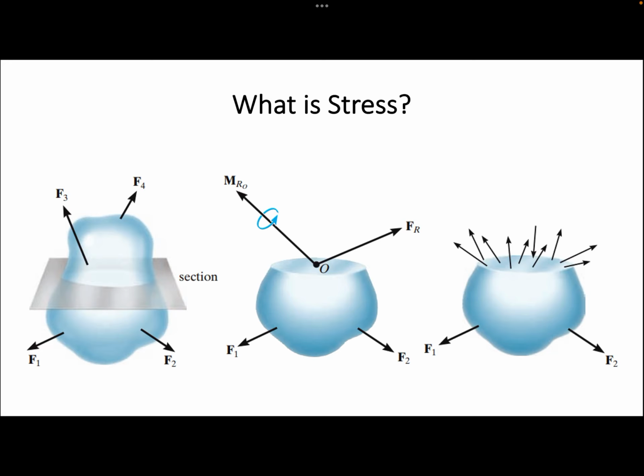find the resultant internal force and moment acting on this whole surface. A problem with this resultant is that it does not tell us the internal force at a specific location and whether the body is strong enough to withstand the external loads. To answer such a question, engineers came up with the concept of stress, which is defined as the internal force acting at each location on a differential area like this one.